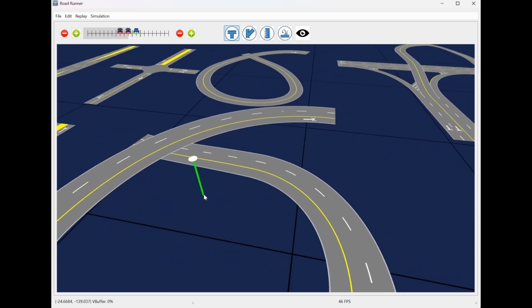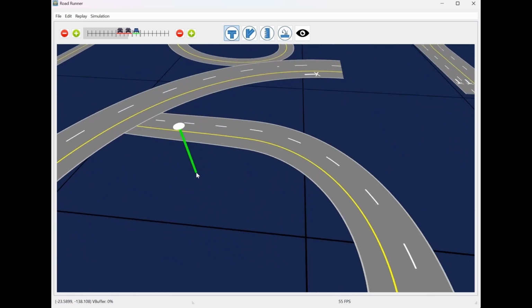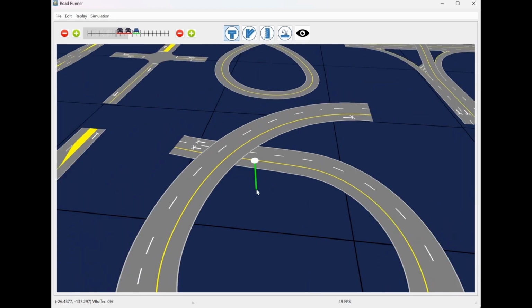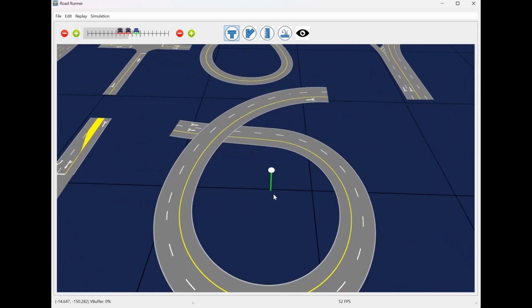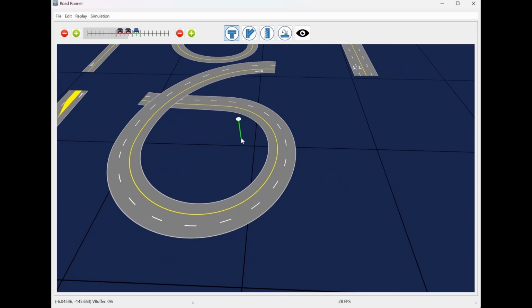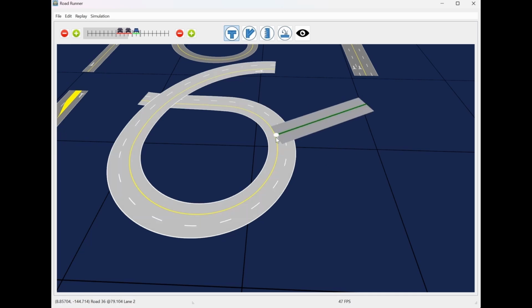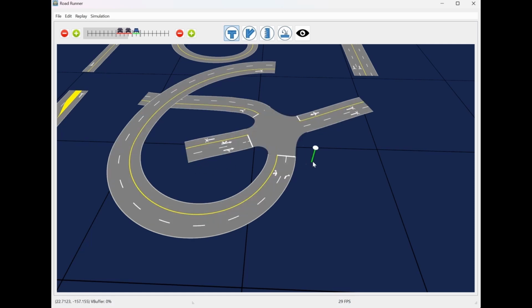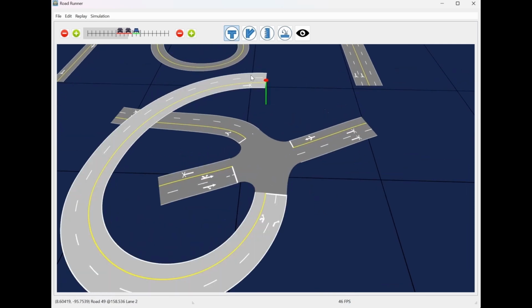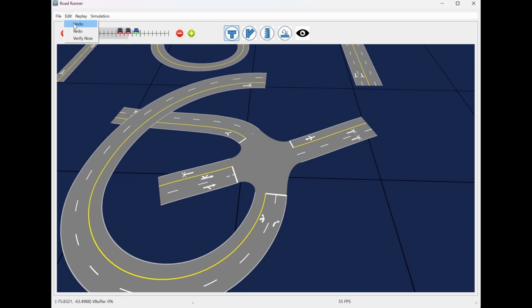And there's a setting that requires at least 5 meters of clearance to make a bridge. So if you fail to provide such clearance, just like this, you will just be creating a junction instead of a bridge. So this section will be a flat junction. So I will undo this part.